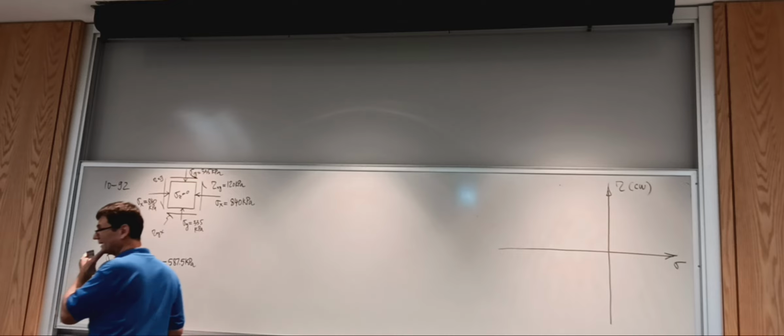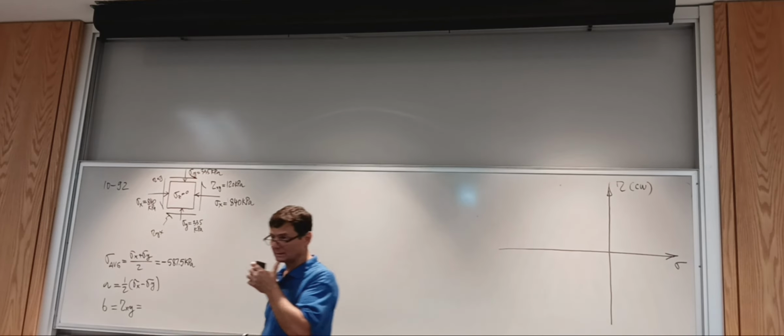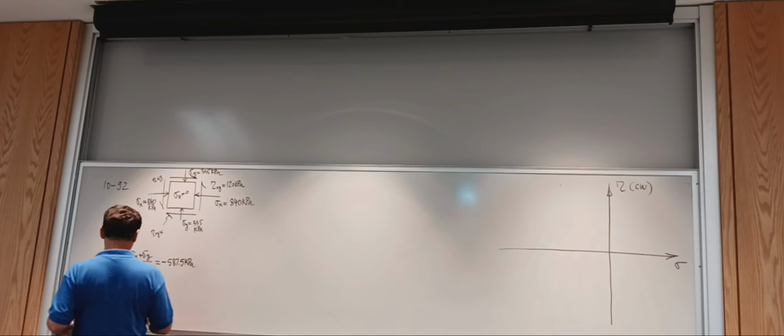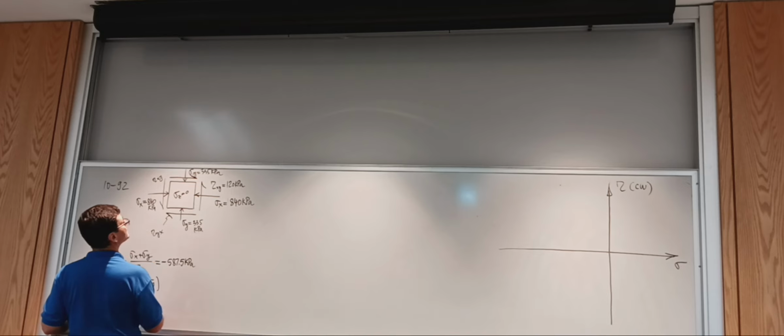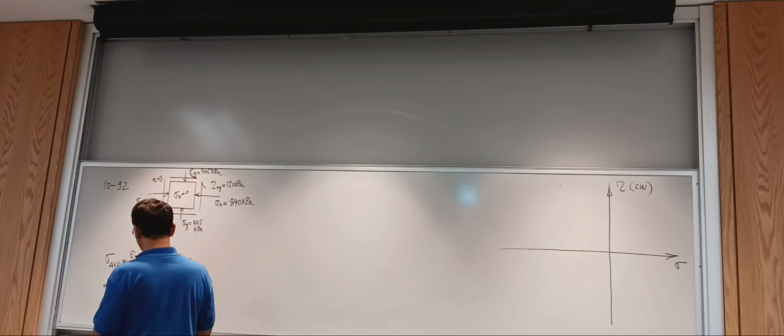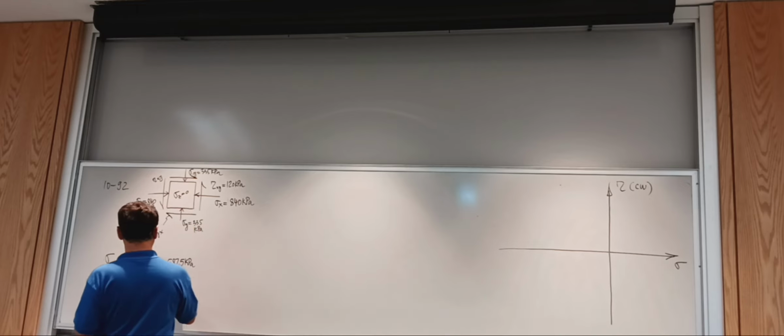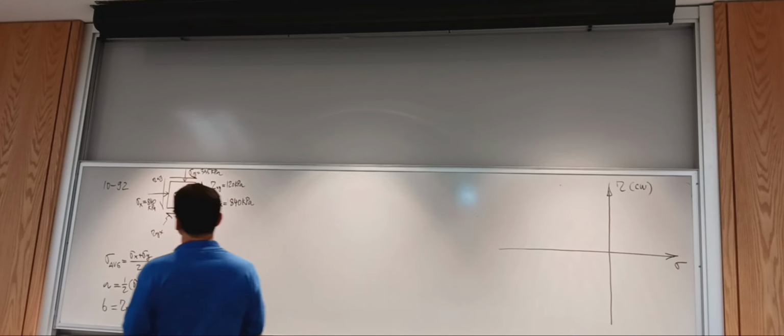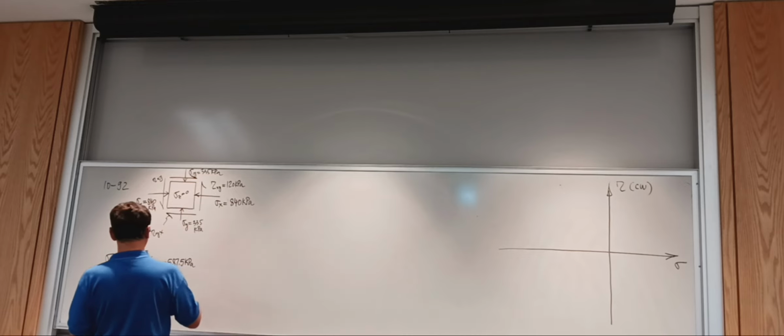Their signs are not important because they get squared to get the radius. Tau xy was 120. And 840 minus 335, over 2, is 252.5, negative, in kilopascals.